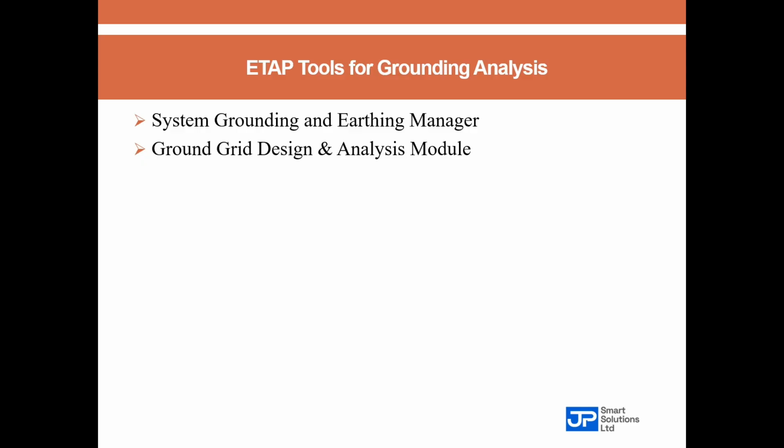Now, this is a feature embedded in ETAP software, ground grid design and analysis model. So thirdly, we have what we call the protective earthing sizing tool. It ensures that your ground conductors are properly sized to carry the expected fault current safely.